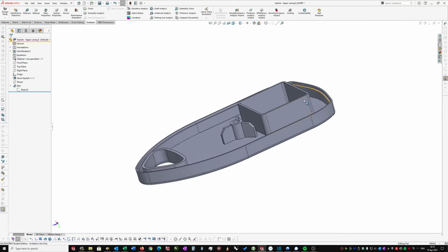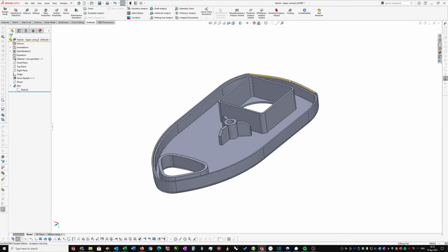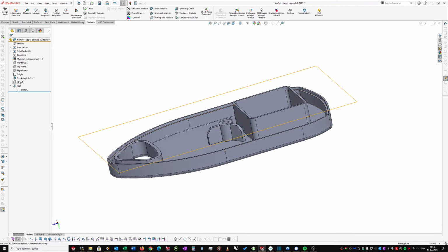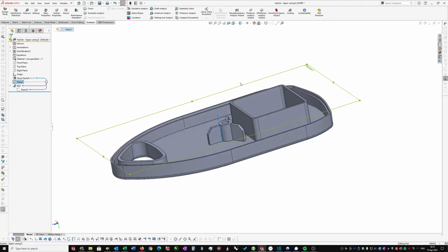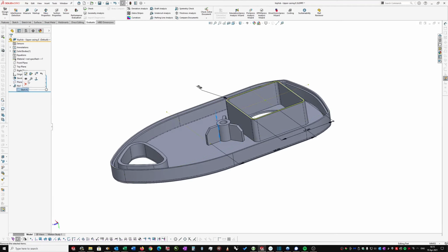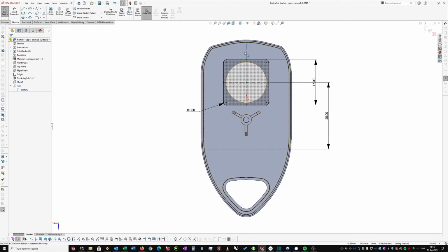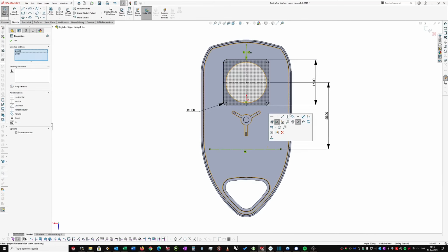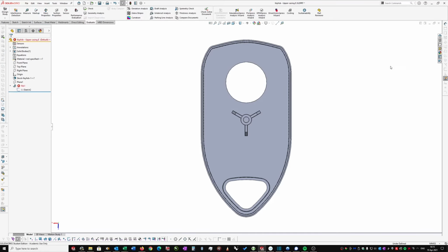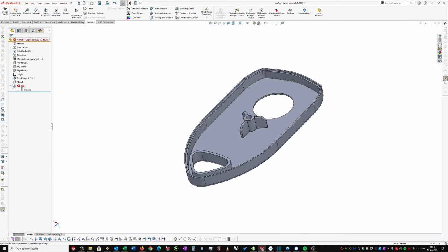And there we go. You can see I've actually been able to make this rib go above the limits of the plane that it started from. That's just because it's a closed sketch. The moment I go and make this into an open sketch again, or reintroduce open sketch elements like these, so I'll make them into proper geometry, it'll give me an error. There we go. There's a nice big red error.